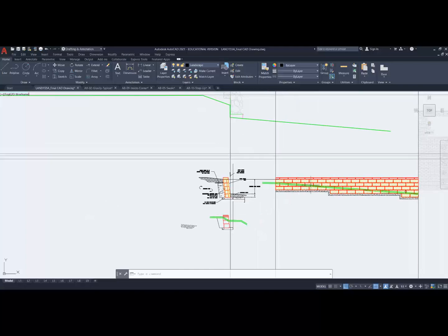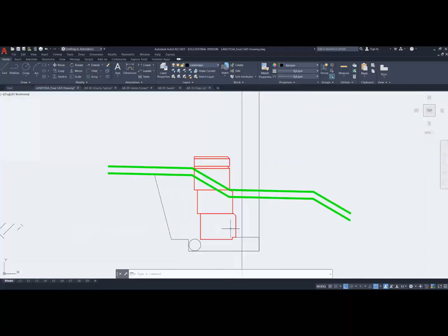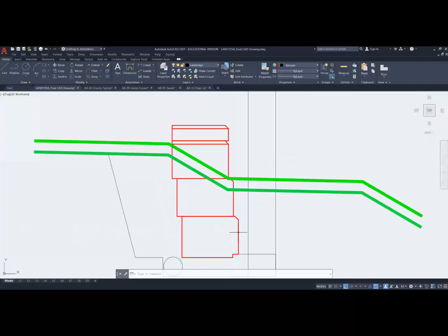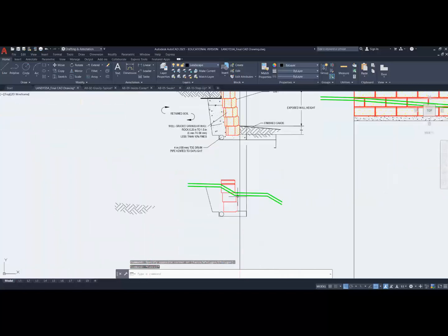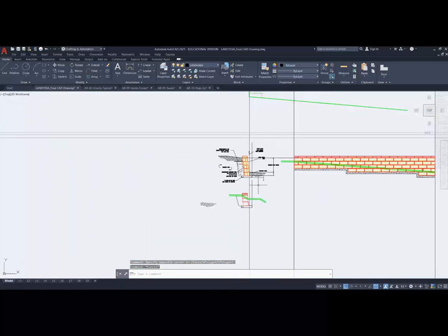So in essence, I've got my side view, I've got my sectional view, and I've got my end view. There's a few things I need to do in order to correct this. This all needs to be hidden line types below. So a lot of this line, like that one and that one, I'll go in and change not my thickness, but my line type to be a hidden line type. Okay. And depending on, you can barely see it here, but in the viewport, it'll come out correctly.